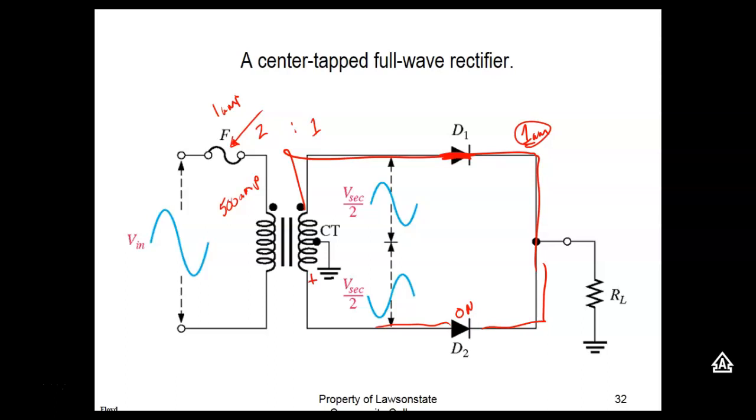But like I said, there's a rating. I'll give y'all, I don't know if I put it on this side or not, where you can actually, depending on the current load of the transformer, what size fuse you should put over there in the primary, and it's going to be a certain percentage. If it was a step up transformer, then the fuse in the primary would actually be bigger than the fuse required by the load.